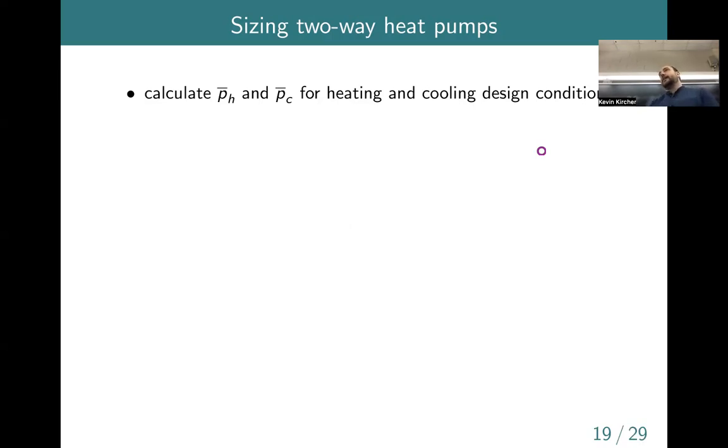And if you're somewhere like northern Minnesota, the heating demand might be way bigger than the cooling demand. So if you put in something that's sized for cooling, you're not going to be able to keep up in winter. If you put in something that's sized for heating, it's going to be gigantically oversized in summer, and that can have some performance issues. Anyway, so there's a few ways to do this sizing.